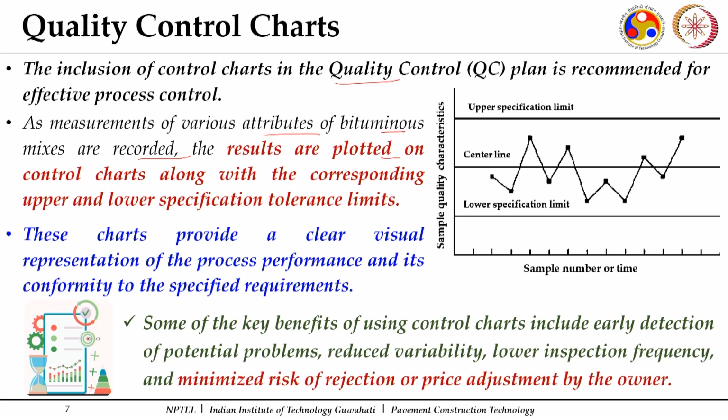and the results are plotted on the control charts along with the upper and lower tolerance limits. So, this gives you, as I mentioned, any particular characteristic. I can see, okay, here this is going along the center line, the target. So, I can figure it out with respect to the control charts of other characteristics what has been there, and then I can pass an instruction and some measure has to be given, so that it can be brought back to our center line.